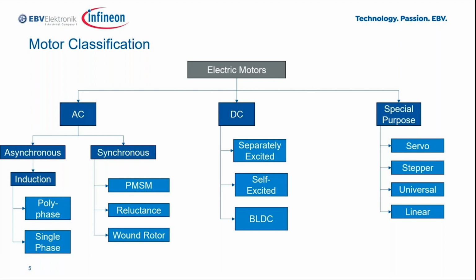And nowadays, BLDC and PMSM motor projects are continuously increasing. Therefore, these two motors are considered to be very similar. While this is acceptable, it can be seen from this classification on the screen that these two motors actually have different structures in different categories, such as AC and DC. We can say that the most important difference is in the back EMF waveform. And let's take a look at the operating principle of the 4 different motors that come from this classification.